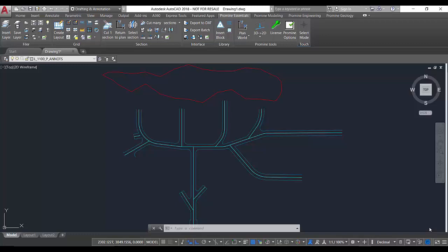Today we'll talk about a very useful AutoCAD feature when wanting to annotate text along an arc. AutoCAD has a dedicated command for this task, therefore there's no need to create an annotation manually and then place it right where the arc is. Instead, it is possible to use the command ARCTEXT.